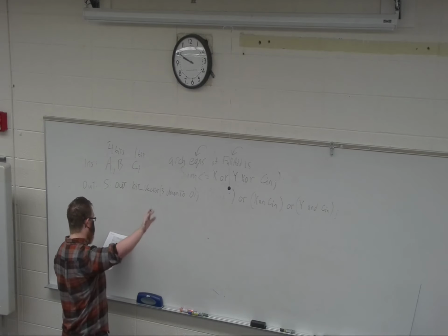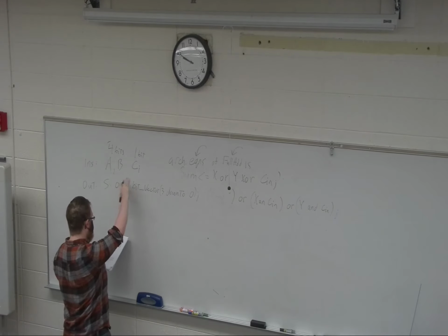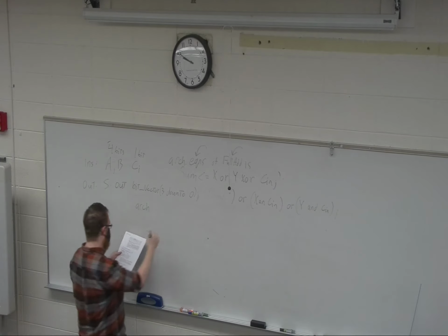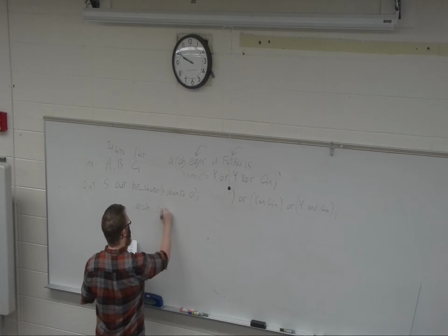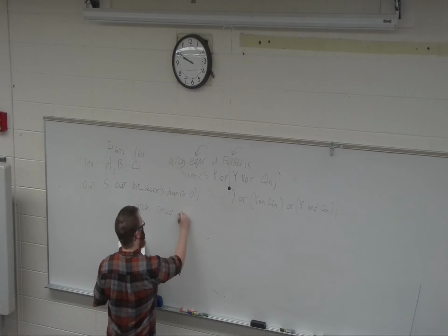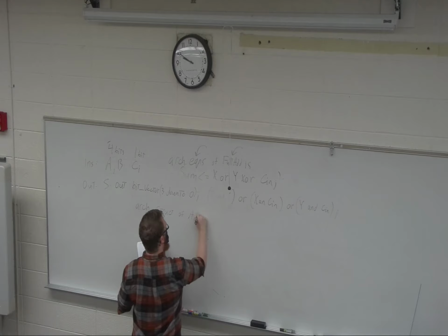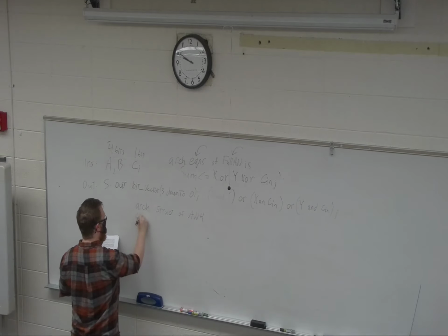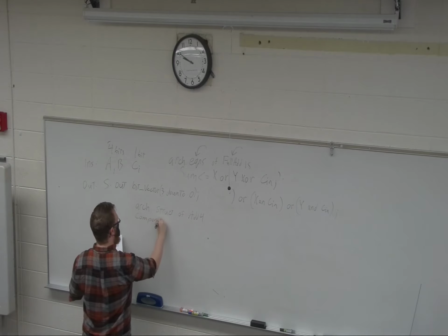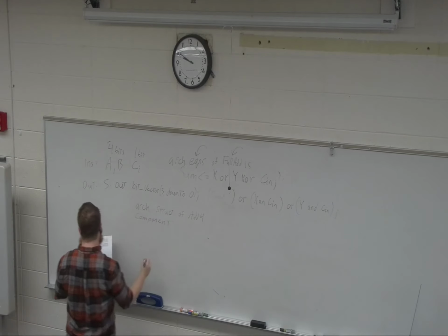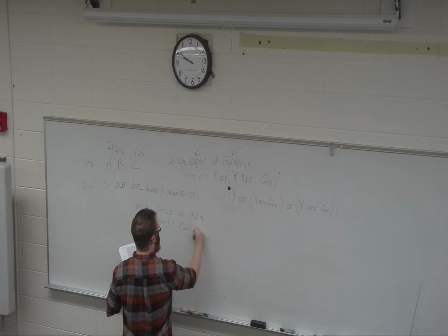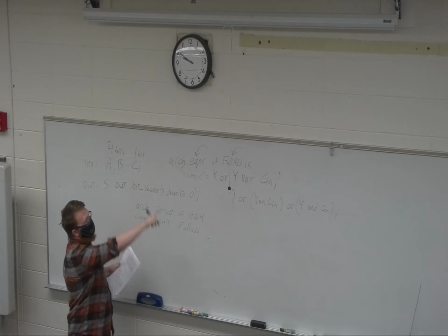So say I've created the entity using these definitions. I create the architecture, which again I'm going to use shorthand rather than writing it all out. We're going to call it struct of add4, and we're going to now let it know it's now a component using the full adder that we built before.